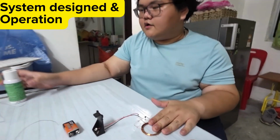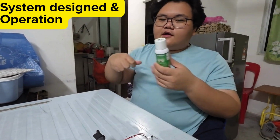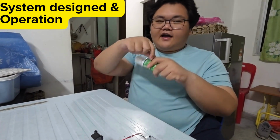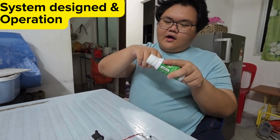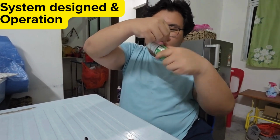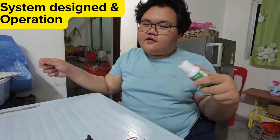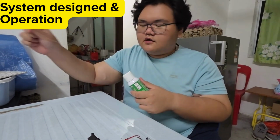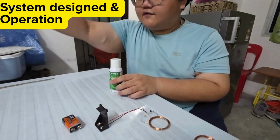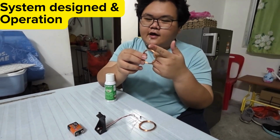How we build the transmitting coil is that we take an enamel wire and roll it 15 times. After 15 turns, we take a center tap here and twist it, and then we roll another 15 times, so it has 30 turns in total. And for the receiving coil we have 30 turns in total, and then just connect it to the LED.